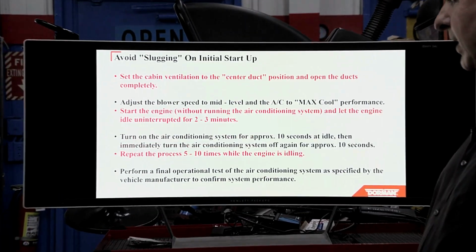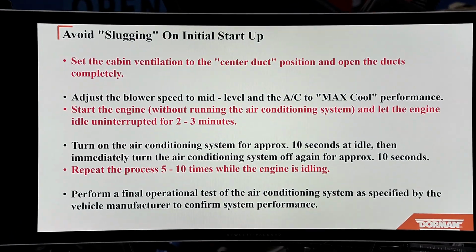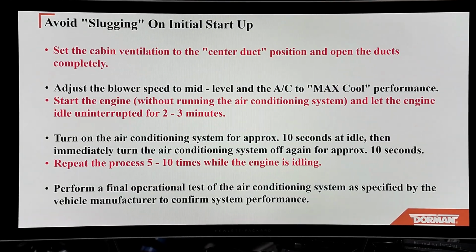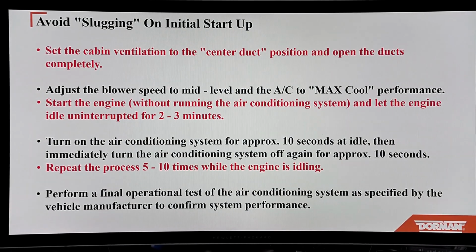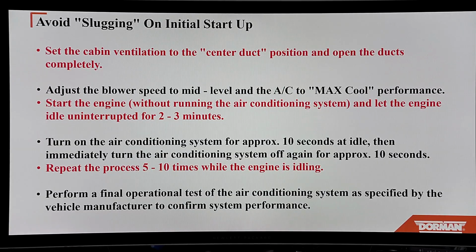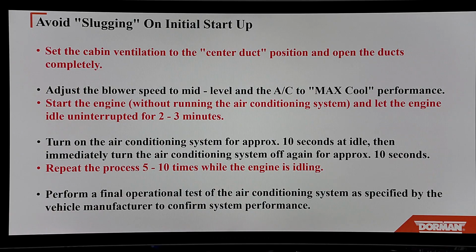So put the right amount in there. Avoid slugging the compressor on initial startup. Sometimes this happens, especially if you charge from the high side. Set the cabin ventilation to center duct position and open the ducts completely. Adjust the blower speed to mid-level and AC to max cool performance.